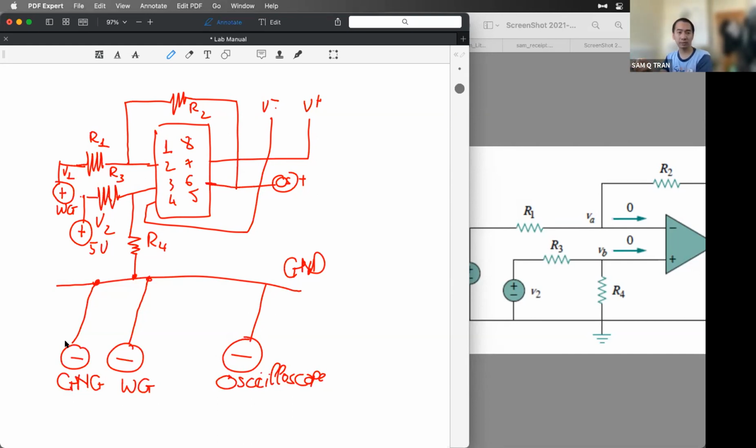So don't worry about that too much, because before you work on the EKG, you will have to work on the thermistor first. It's the toned down version of the EKG. The thermistor will measure the temperature in the environment or in the water, and then it will return a voltage value for you guys. You will read that voltage value and use the info sheet to translate it into Celsius or Fahrenheit or Kelvin. It depends on the type of thermistor you are using.